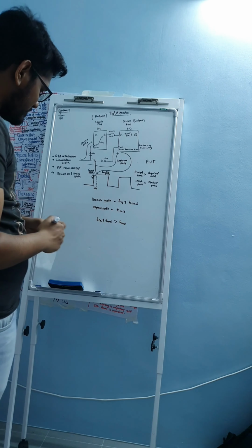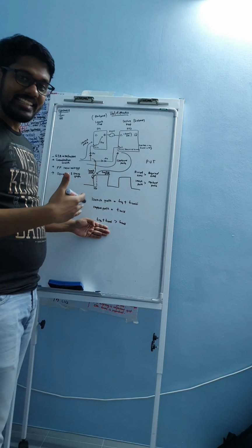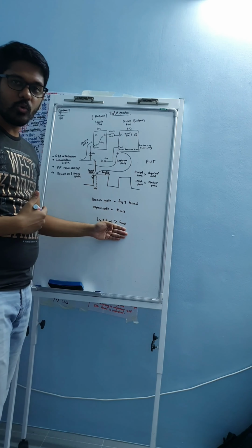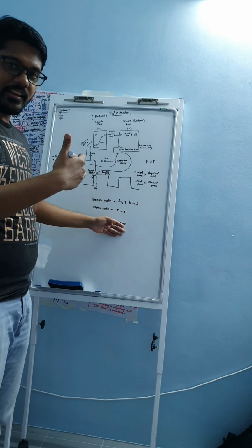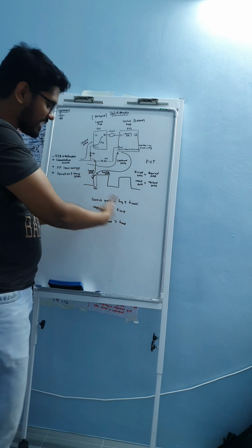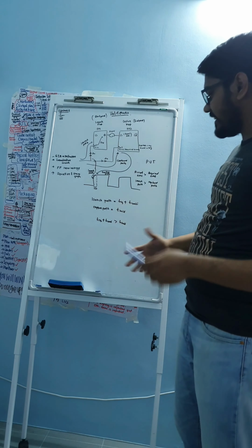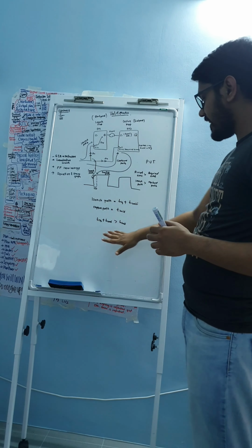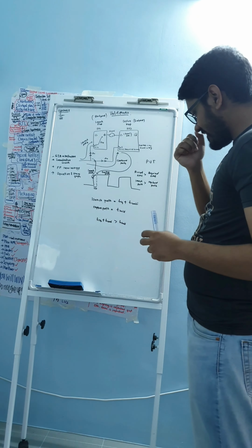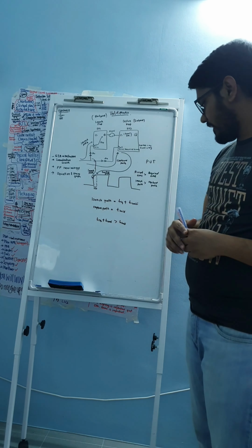So it means that your data is coming later. It's delayed by an amount of T hole; once T hole has been met, then after that it has to arrive. So in other words, you just have to make sure your data arrives later. If the data arrives early, then you're going to have a hold violation.